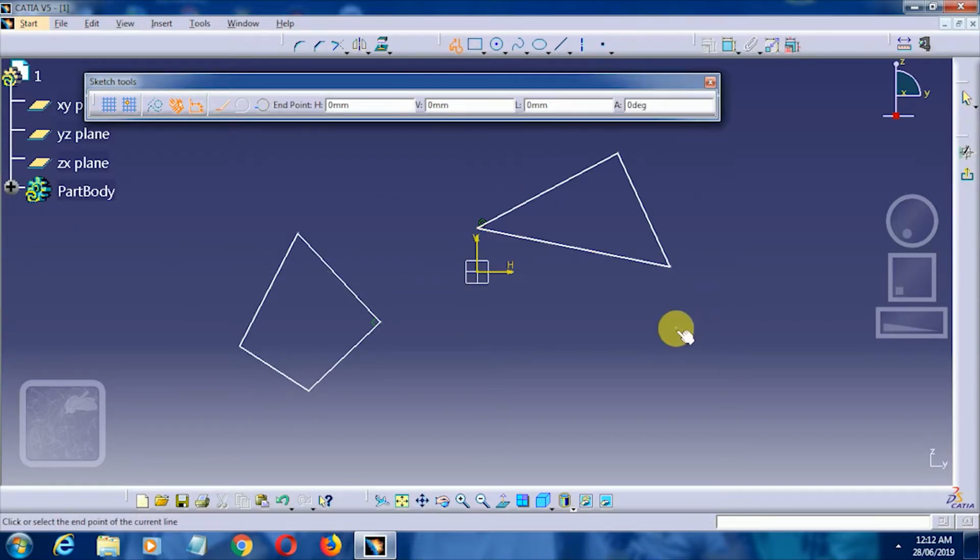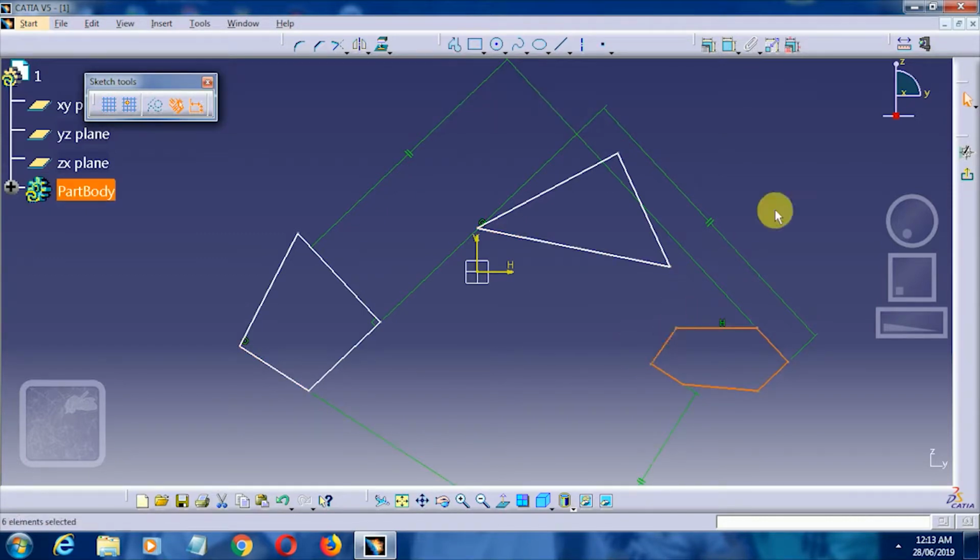Now I can just simply use another one. I can create a pentagon. Here we can see these are different options that are developing. These are only because we have kept the option of geometrical constraints on, so we can see some geometries that are being there. That is, this option highlights the parallelism between two lines. This option is there as well. So here we can see, although it has a number of sides, it is still a closed area. So this is what we require.